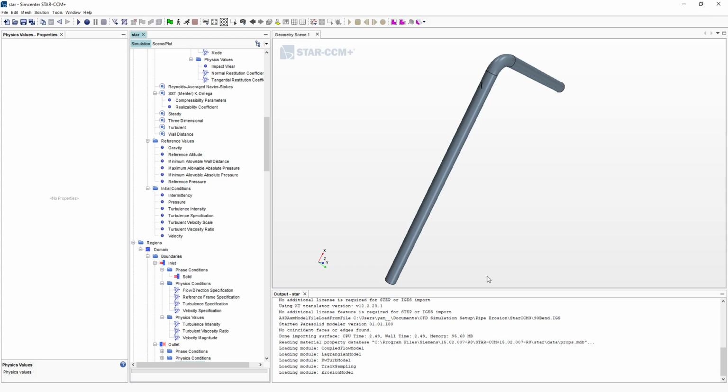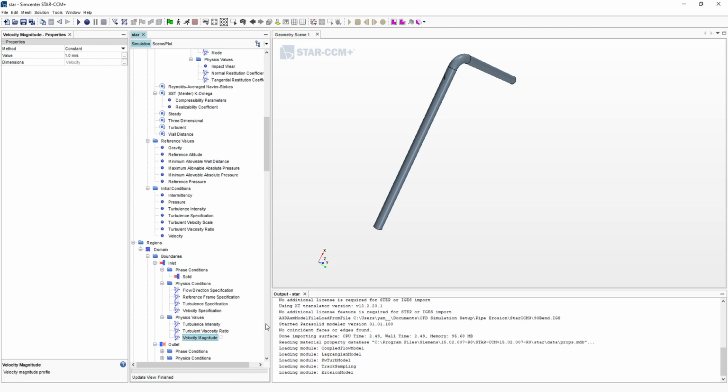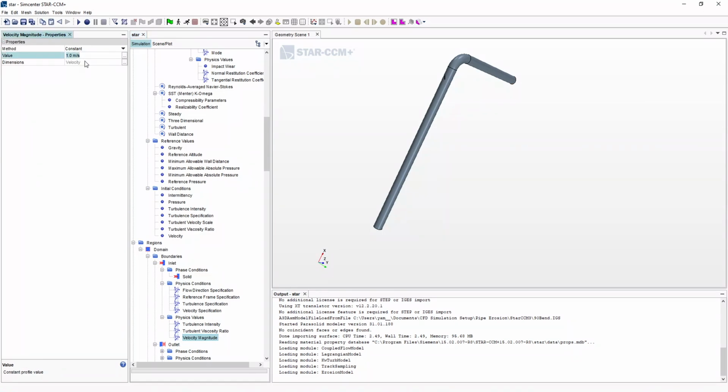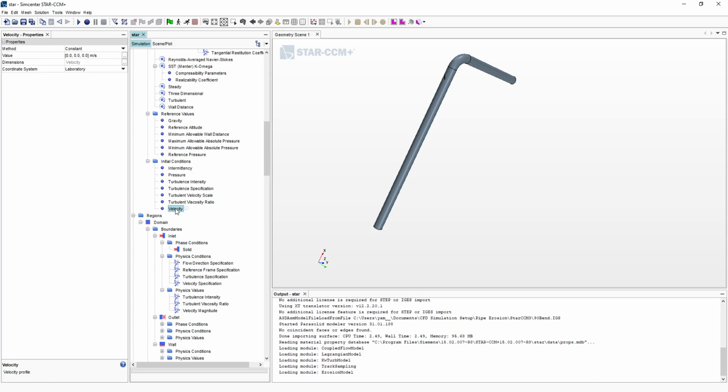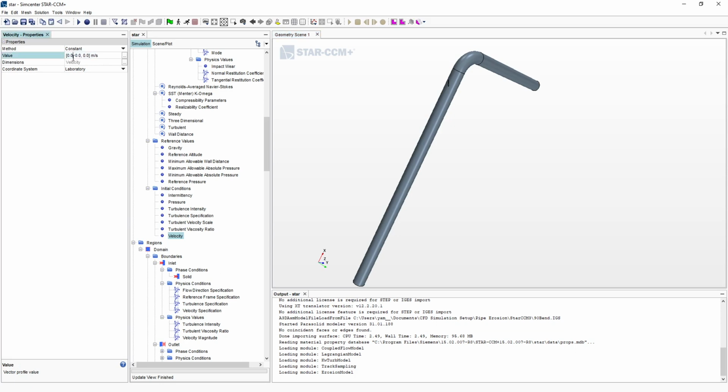Now you need to specify what is the velocity. Velocity for your inlet, we are looking at 34.1. So you can specify here to be 34.1. The direction is normal to the boundary. So you can specify your initial velocity as well. You can say that your domain has initial velocity everywhere, same as your inlet initially. Maybe you put it as 30.